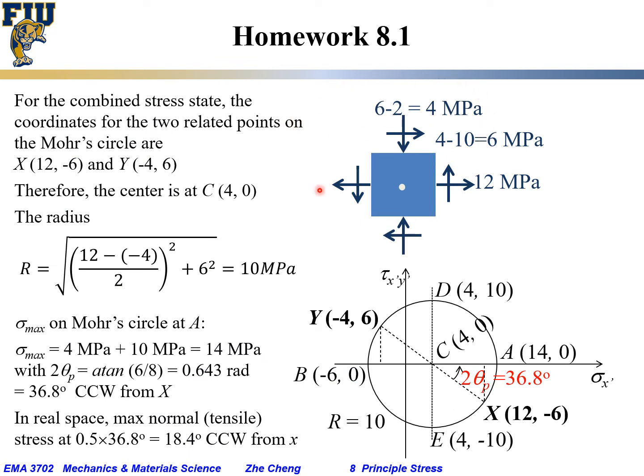Finally, we have this combined stress state, the stress state from the superposition of the original two stress states, one on the left, one on the right. The right one we did rotation or transformation, and then we did the superposition or addition for the two to get this stress state. The last step is to determine the principal axis and the principal stresses for the combined stress state.